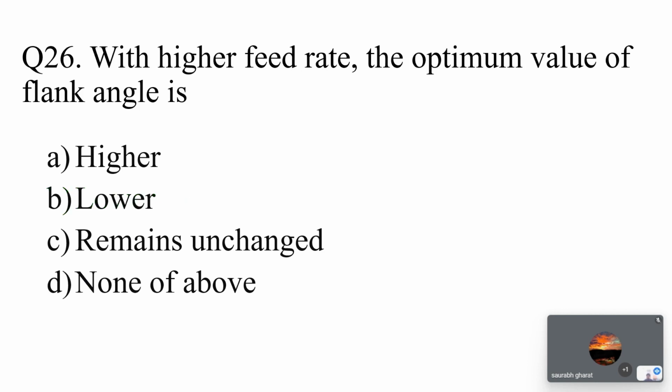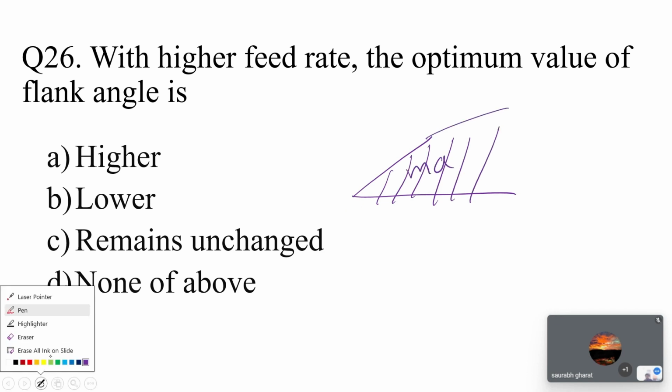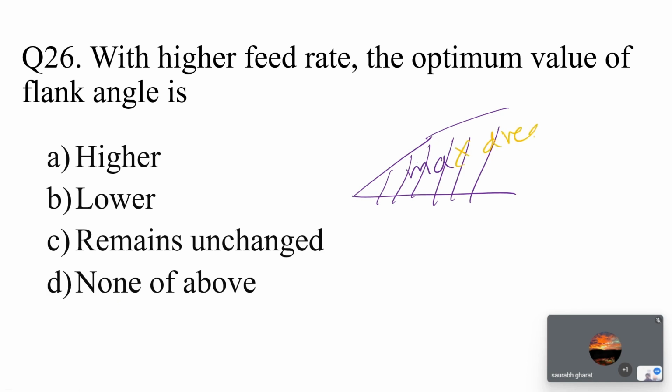Again, with higher feed rate, the optimal value of flank angle is? As your feed rate increases, the strength of the tool is important, so maximum area for strength is required.